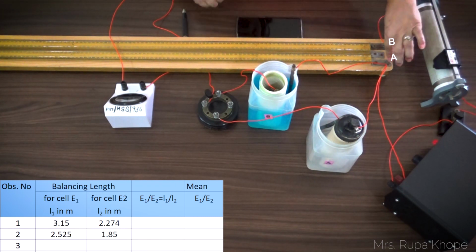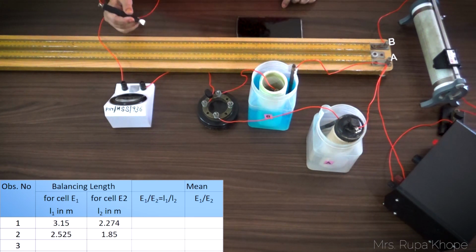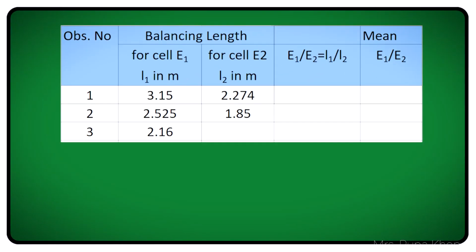So now the voltage drop is more. Therefore the potential gradient, which is voltage upon length, will increase and therefore again the length is going to decrease. So I put on E1, take the reading again, it is 2.16, and then I put on E2, I get the reading 1.59.